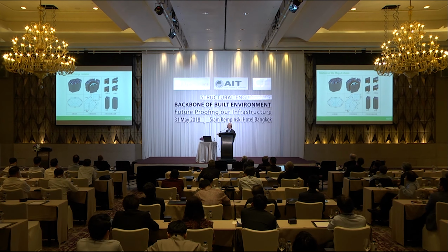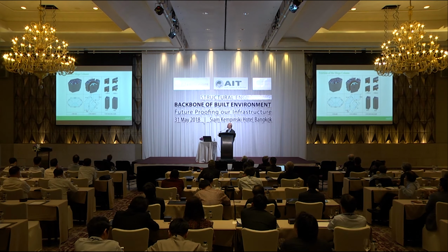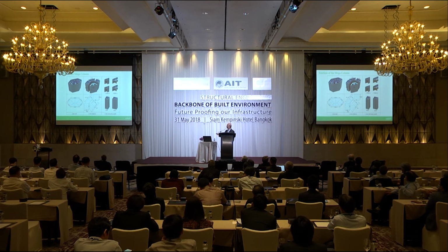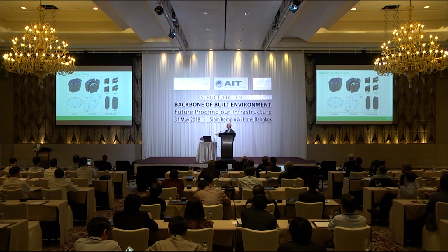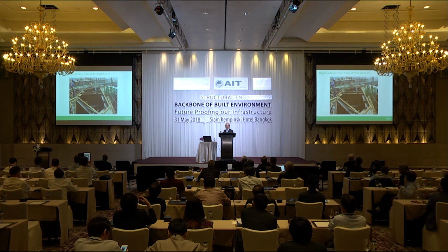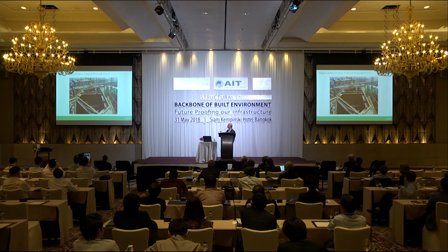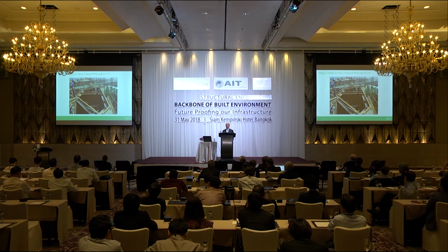And also you can see this is the drawing we suggest for how to make this what we call the multicellular composite column. So that they can fabricate it in the shop and then weld it on site by each 4 pieces, right? This is the example. This is the on-site example. This is a worker, a laborer there, and you see a big box.